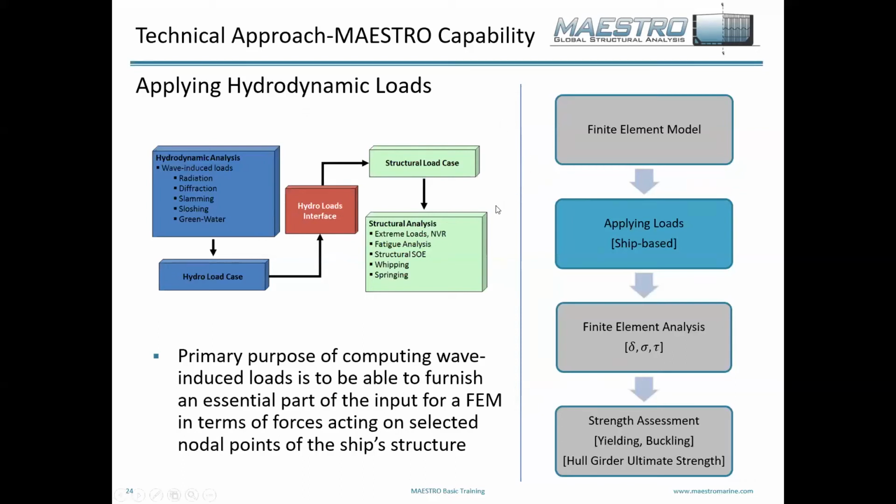And you can get your extreme loads, the fatigue. This can be used for helping to determine what your structural safe operating envelope is, or to analyze whipping effects if you do a time domain analysis.